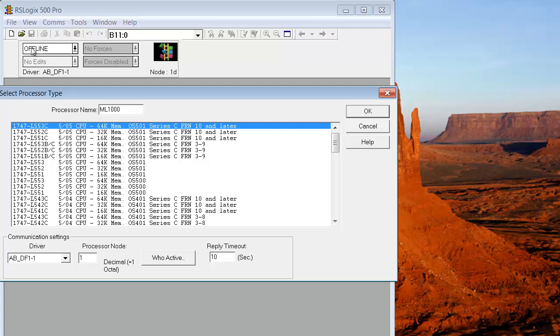But before we do that, let's look down through this list. You can see the first handful here are all Bulletin 1747 processors. These are all SLC 500 or 505s, as we say. Till you get down here, then you see 504. The 505, the SLC 505, those all had two COM ports, RS-232 and Ethernet.